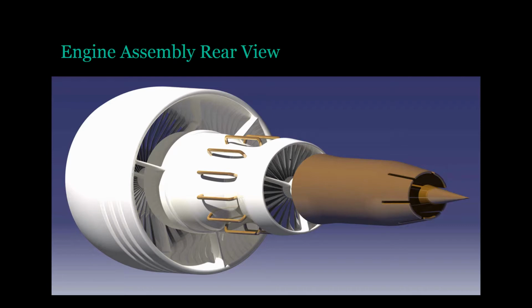There is a connection set in front of the middle casing. This stabilizes the front fan used in the turbofan engine. There is a connection set between the front casing and the middle casing, and there are also connection sets inside of the middle casing that lock the drive shaft into place. There are also connection points inside of the rear casing, however they are not shown in this view. These connection points are very important to the engine's overall efficiency and stability because they limit vibrations and they keep everything rotating around a central axis.